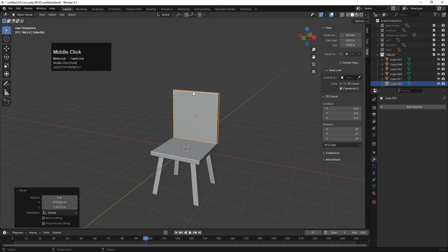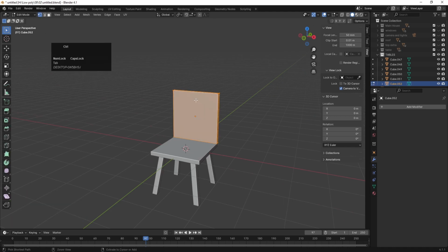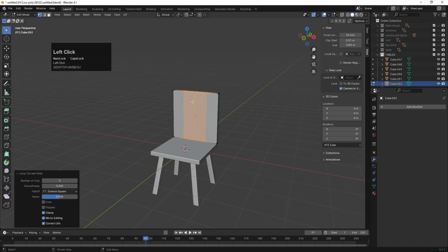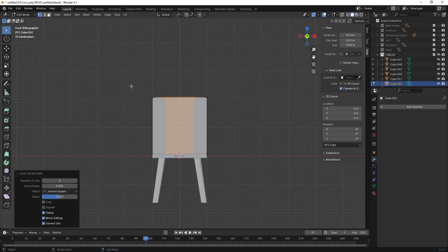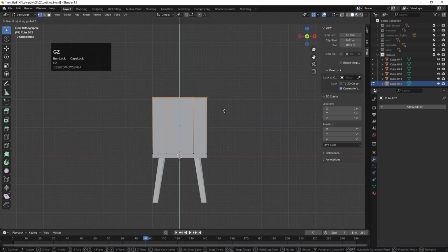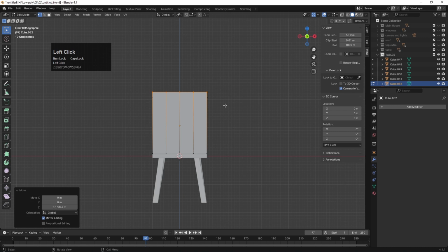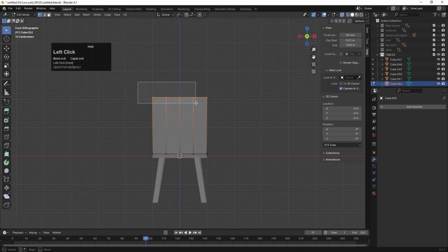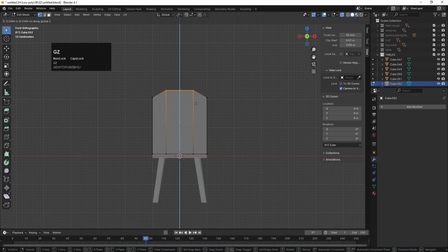And if you want, you can go to the tab view, hit Ctrl R, you can create 3 points over here like this. Then let's select this, G, Z direction, Alt Z, select not this but this much portion, G, Z, and move this over here like this. Select this, G, Z, and let's move this over here.